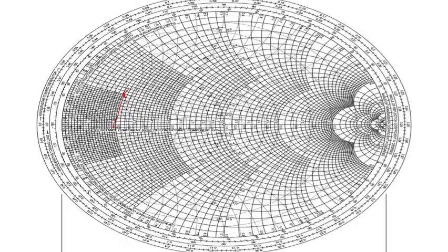So we are supposed to plot the impedance. For plotting the impedance, first along the resistance line, we plot 0.2. That 0.2 is already plotted for you. That 0.2 will be plotted up. And the impedance was given plus J 0.2, so that impedance also is plotted over here. I hope you understand. This impedance has been marked. Can you all see this? So this point is our impedance plotted, that is ZL, which is 0.2 plus J 0.2.